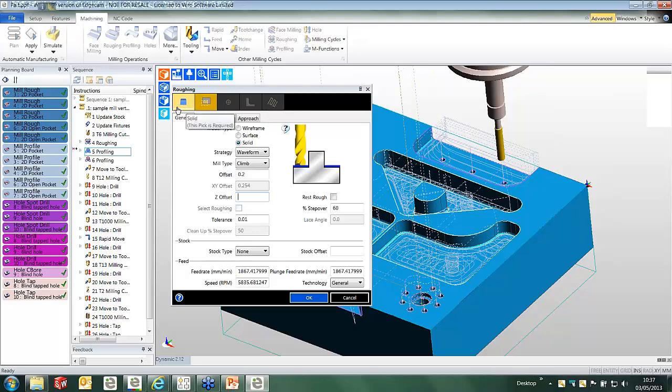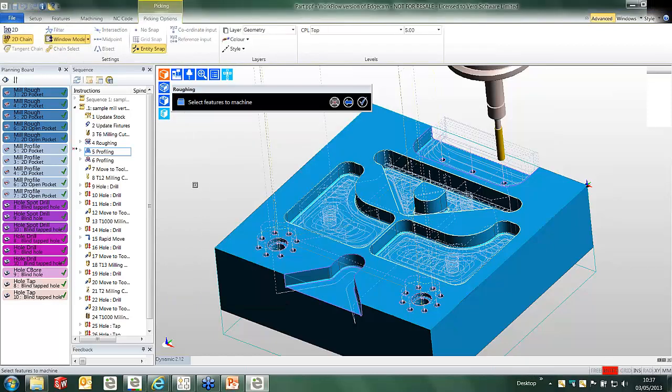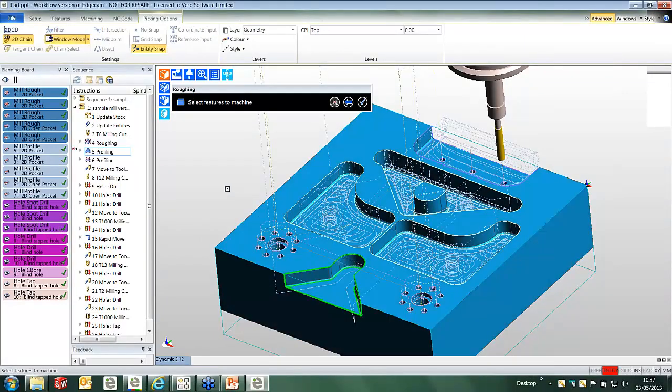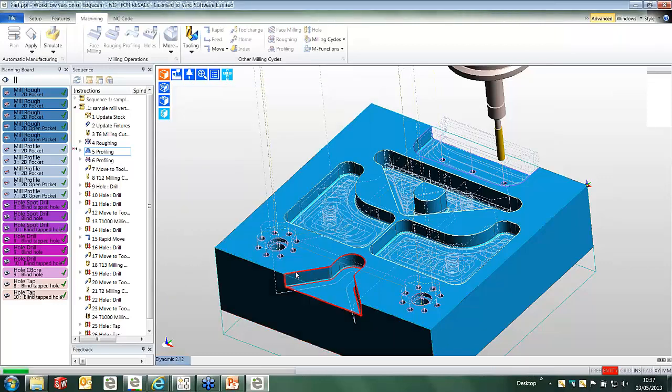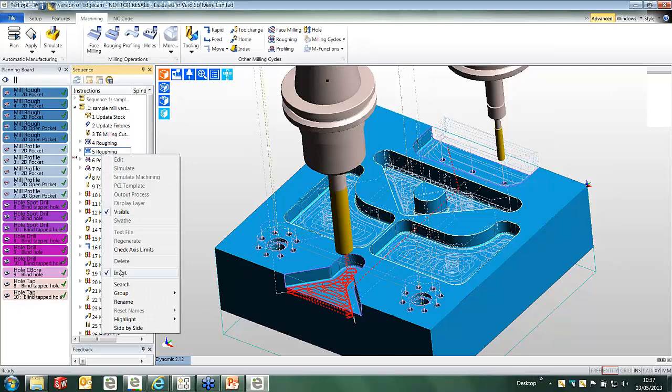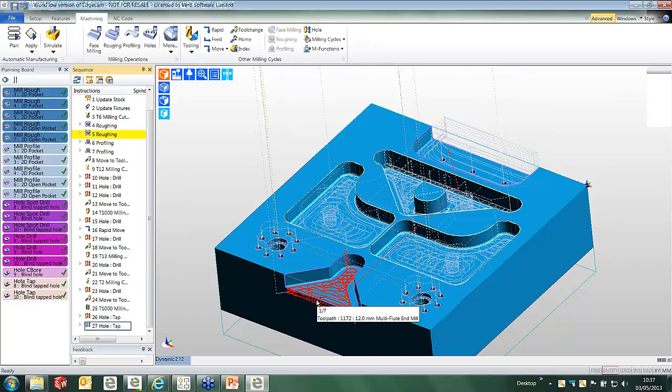I have a prerequisite here, which must be I must pick some geometry. So let's interact with the first button. The feature to machine is the open feature. Once we've acknowledged that, you'll see that we have a tick, which is just confirming the selection, and we can move ahead. A boundary. This is an optional preference. You'll see by the designated underline, I must have geometry to machine. However, I don't necessarily need a boundary. So let's move ahead and apply the toolpath. Very quickly there, we see that I've now redeployed my own custom toolpath.